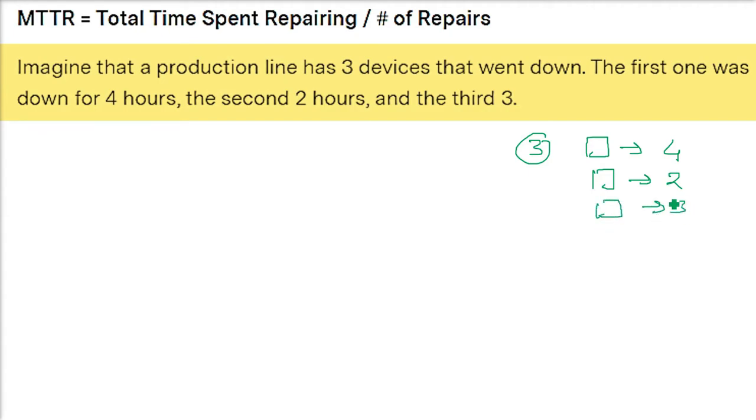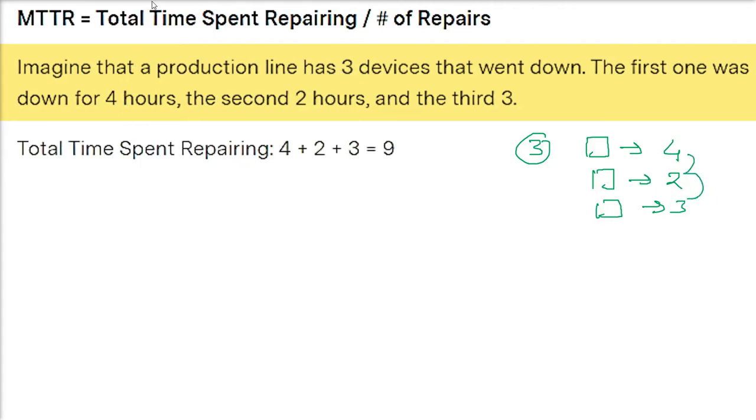What is the total time spent in repairing? 4 hours, 2 hours, 3 hours, add them. 9. What is the number of devices? 3. Divide 9 by 3, you are going to get the MTTR, which is 3 hours.